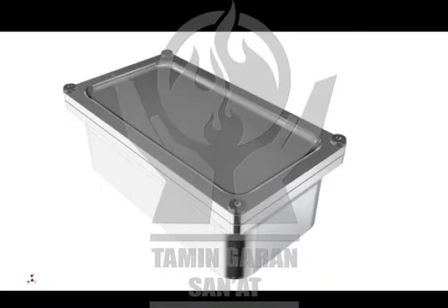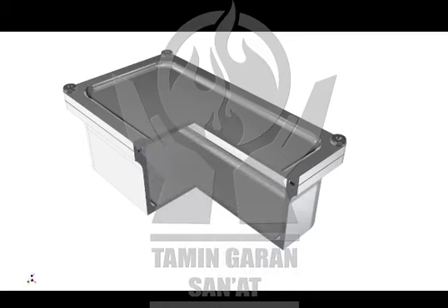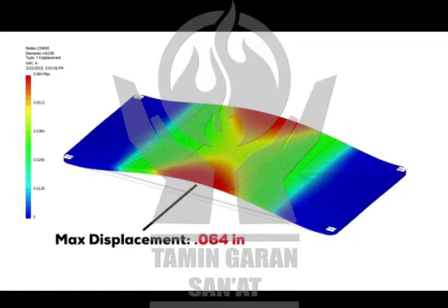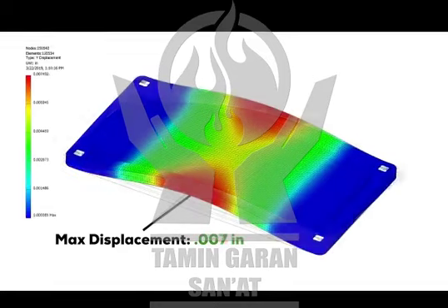Another configuration is a face seal, which you might use when trying to seal an enclosure. These are really a type of gasket, and they require a clamping force, usually provided by fasteners, to compress the O-ring. Face seals are actually really tricky to get right because squeezing the O-ring requires a great deal of pressure. The first lid design is far too thin, and in the middle there's virtually no squeeze on the O-ring, and hence no sealing. We can fix this design by adding a lip around the perimeter.